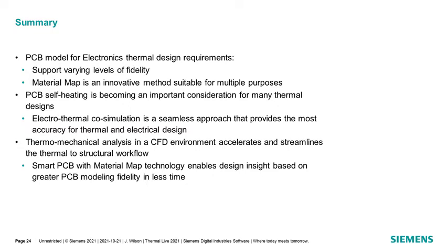And the Smart PCB with the material map technology enables design insight based on greater PCB modeling fidelity in less time. That modeling approach allows you to build a very detailed thermal model, and the finite element model generated from that in FlowFD, using that same nodal topology, greatly speeds up the mesh generation time and allows you to model that PCB in a lot of detail very quickly.